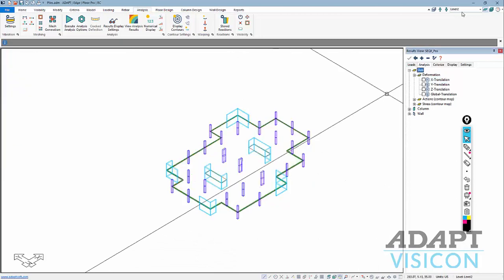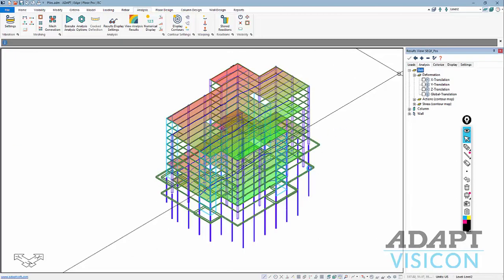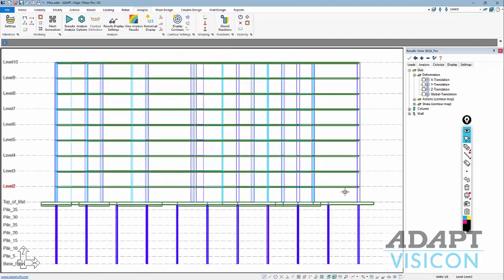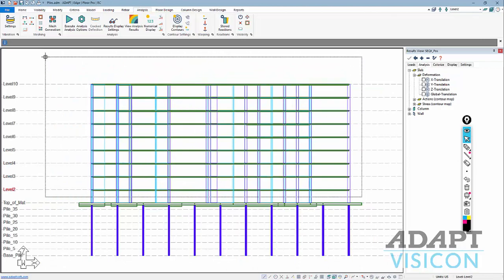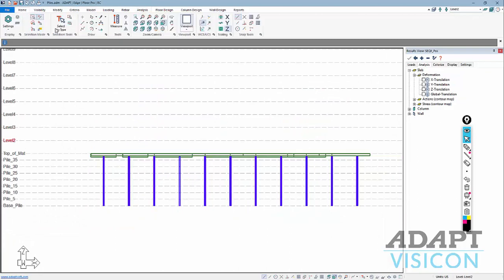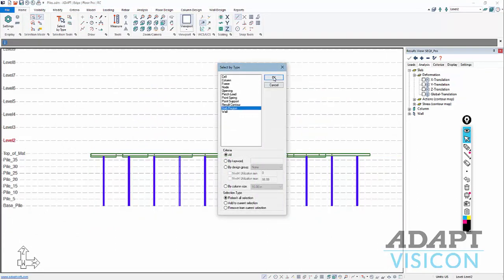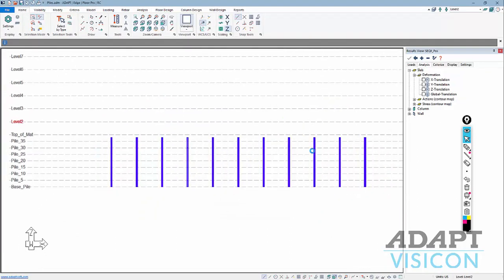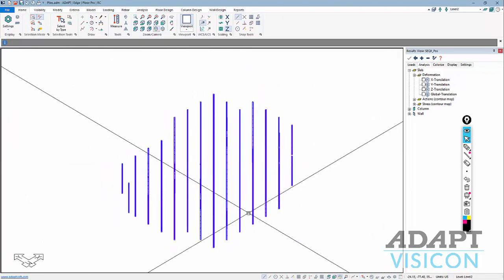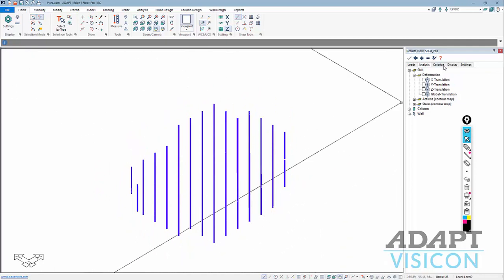So I'll turn off the deformation. I'll go back to global viewing of the structure. I'm actually going to select everything above, and I'll just hide that. I'll select my slabs and choose to hide that. And now I want to look at my axial reactions in my piles. So we'll go now to, for any load combination selected here, including the envelope.